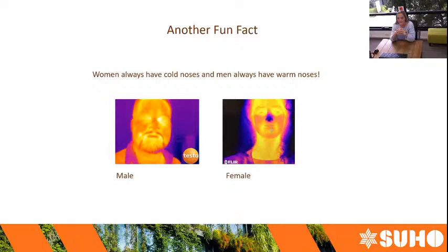So those are some basic things that we find when we go into a residential dwelling and depressurise it. We find leaks, we find missing insulation, and we find thermal bridging. They can appear in different ways in different buildings, but those three things are generally present.